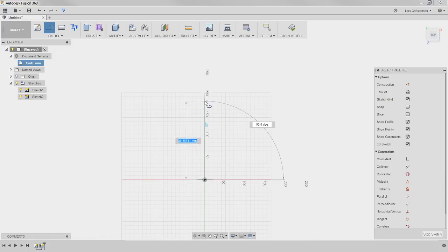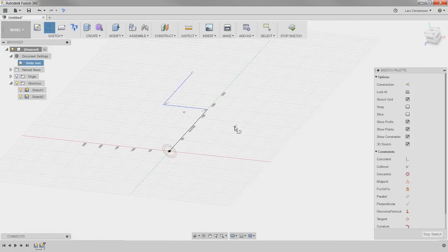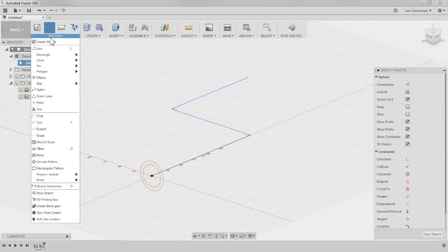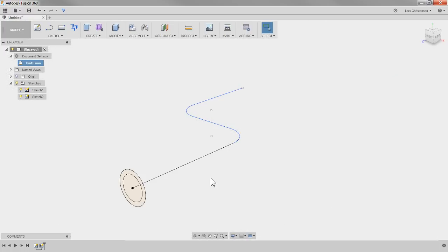This is not really important. Sketch this out, something like this, and you could choose to just make it straight. I'm going to put a couple of radiuses on the lines here. Go back into my sketch and add some fillets. I don't know, just because I like it, I guess. Add some fillets like that, and stop that sketch. So we have two sketches. I didn't define that one, I should probably put some dimensions on it. So we've got two sketches, profile, path.